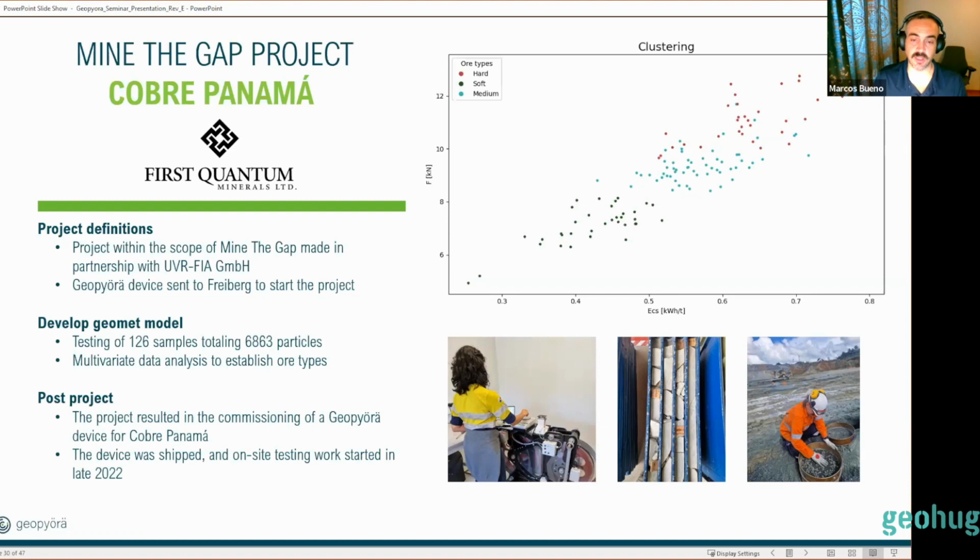They have results immediately to inform the drill and blast team, so that they can optimize the drill and blast by loading harder zones of the bench with higher loads of explosive and the softer, more friable areas with less explosive. They can also track this ore hardness information all the way through the mill feed. And we are developing predictive throughput models for them.